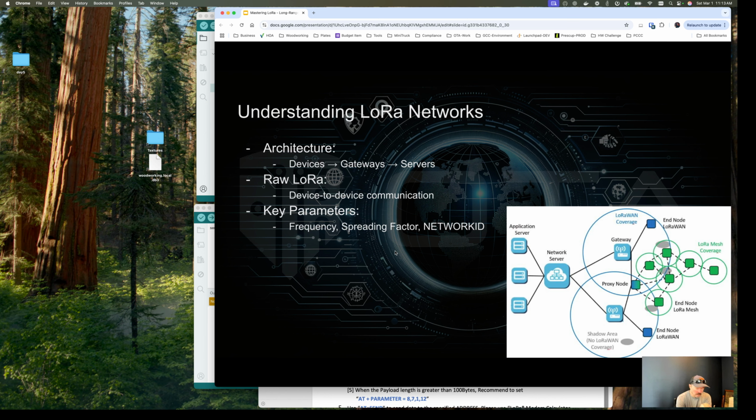But when you're setting up your radio, whether it's programmatically, like programming the code with an MCU to control it, or you're doing it yourself, there's a couple things you need to consider. One, you need to buy the right frequency for your region. Legally speaking, that's 915 megahertz here. So make sure you get the right frequency for your region, so that you can legally and safely operate.